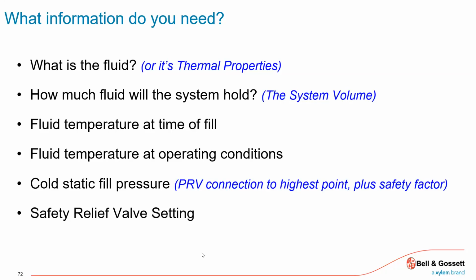Anyways, what do we need to size an expansion tank? We started talking about it. Water or glycol water, what is the mixture of the fluid? What's the volume, temperatures, fill pressure, and then our relief valve setting.